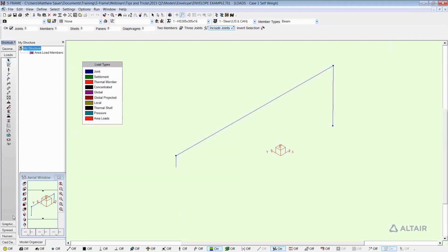Now I want to show you the loads that are on this structure to get a better understanding of what we're working with. We have a self-weight load case, which is considering the effects of gravity. We have a live load case that we can see here, has 100 kilonewtons per meter, and a snow load case that is a partially varying distributed load that tops out just at the top of this one column on the right-hand side.